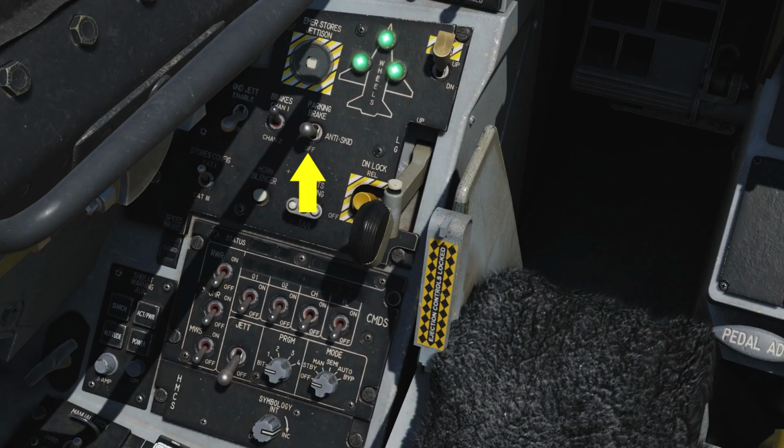Note that the parking brake does not use hydraulics, but rather a clamping mechanism which requires battery power to initiate. The tow brakes can be initiated by either electric channel 1 or 2, which both operate the hydraulic valves. You normally keep it set to channel 1. The emergency jettison switch will dump fuel tanks, suspension racks, as well as free fall ordnance.